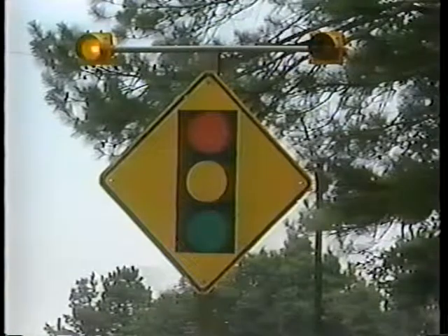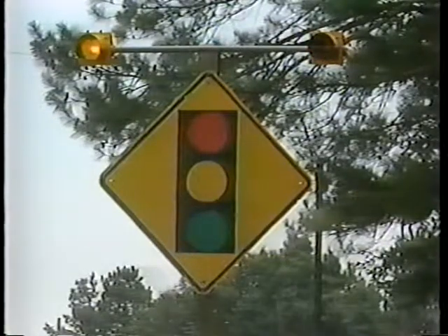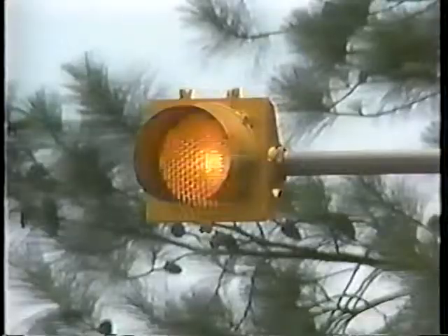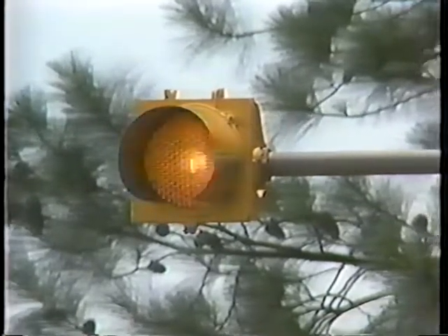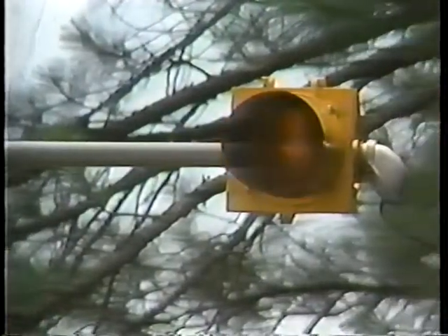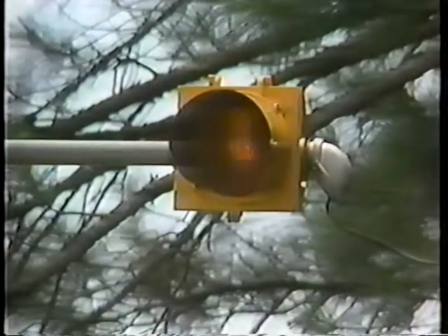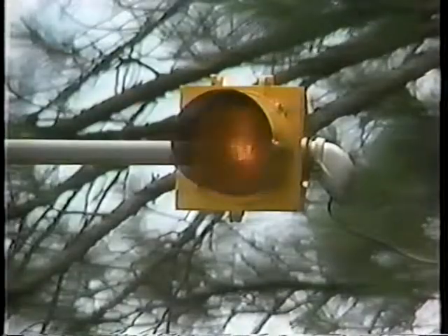Flashing hazard identification beacons are used in work areas both day and night to alert drivers of a critical point in the highway, such as a truck crossing, and have the same meaning as permanently mounted beacons. Flashing beacons are not used for channelizations.